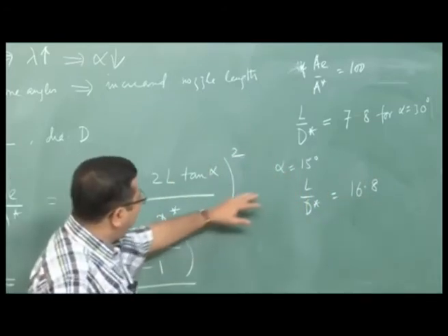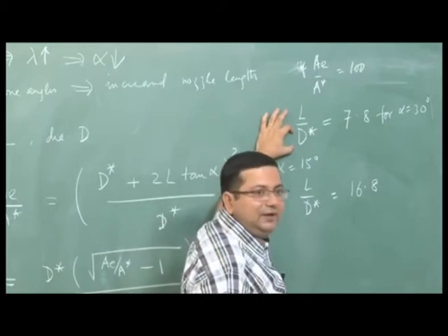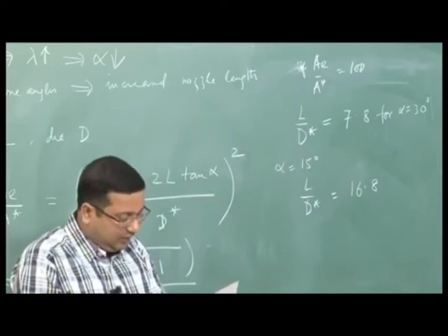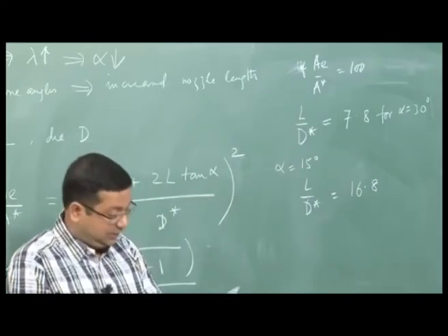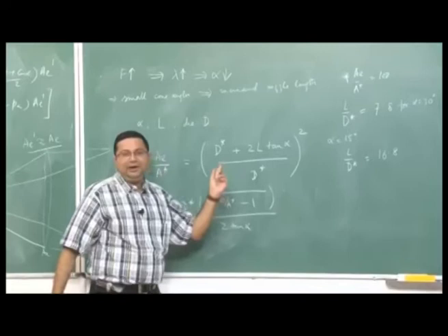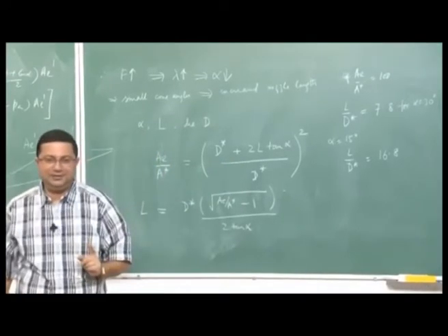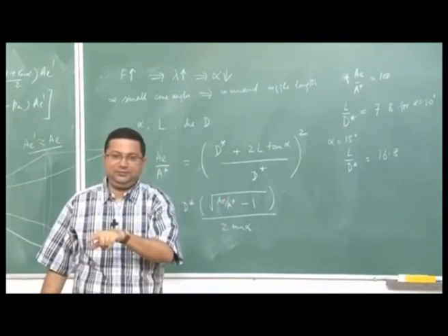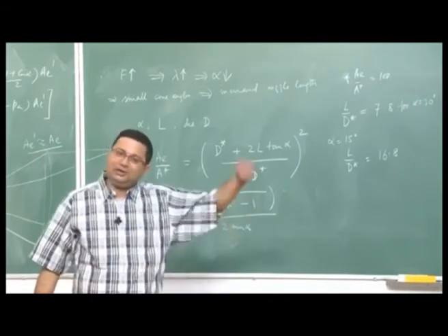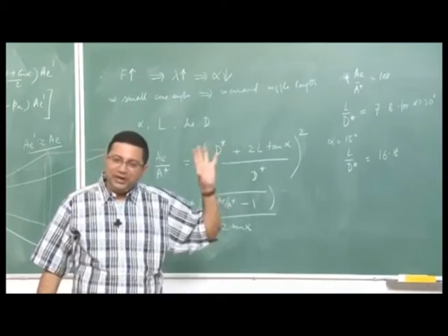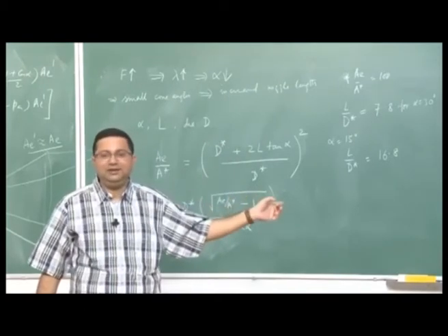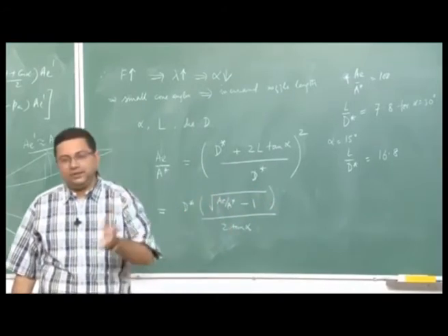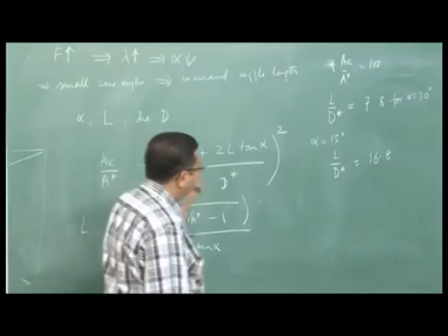Once again, D star is the same. We do not want to change D star, that is the throat condition, because this D star is the throat diameter. Remember our discussion in the previous class, the chamber pressure is maintained by this. So that we cannot change, otherwise the chamber pressure is going to change. We have the chamber pressure P_C0 maintained by this D star, which will dictate the chamber pressure, the combustion conditions as well as the specific impulse. We do not want to change that.